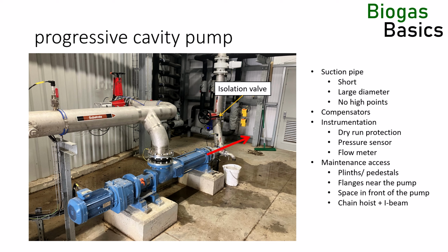It is also recommended to place a drain near the pump. This area will get messy during pump maintenance, and in case any civil engineers are listening, the drain must be at the lowest point of the room.